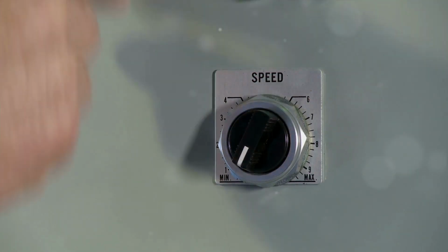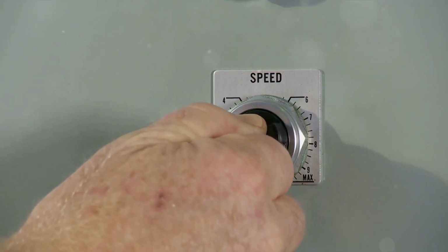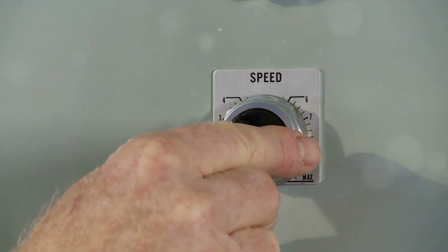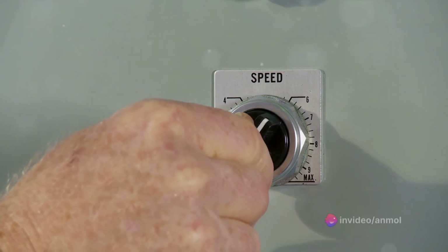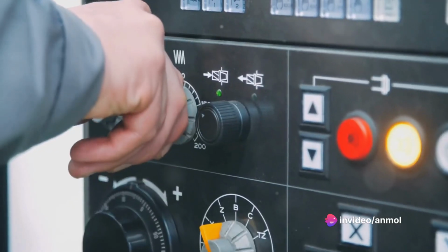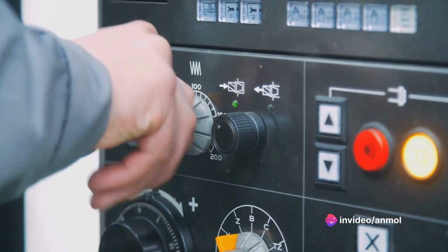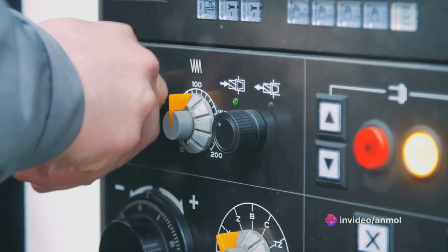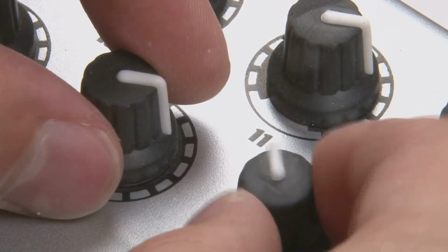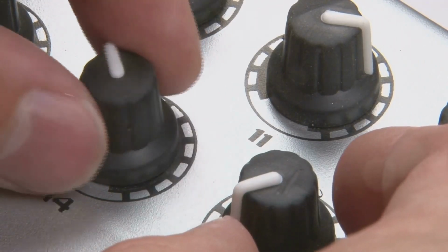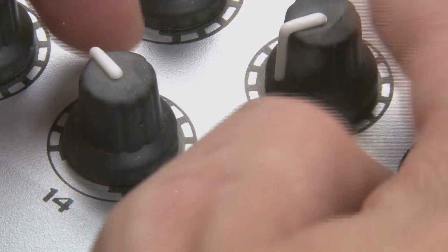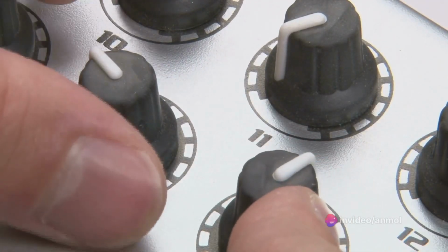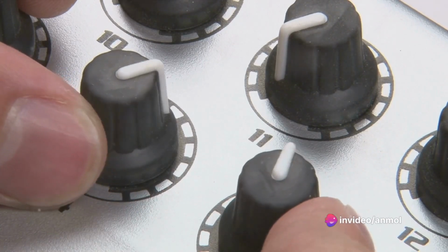Next, let's talk about adjusting the VFD settings. This can often resolve issues, especially those related to performance or communication. You may need to adjust the speed, torque, or voltage settings, for example. Always refer back to your VFD's manual for specific guidance. It's a treasure trove of information and can provide the precise parameters to get your VFD humming along smoothly again.